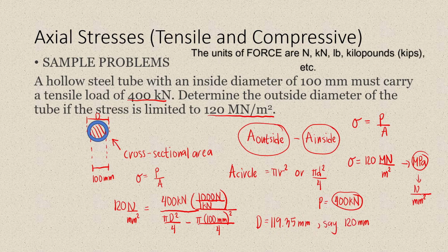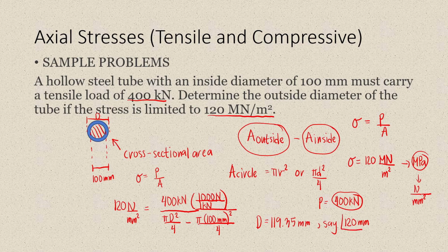Now again, when asked for the area or dimension, always round up, because having a larger area will reduce the stress in the member and it will ensure safety. And so this is our answer.